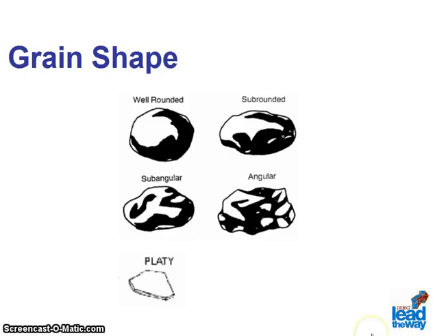When examining samples for grain sizes, the shape of the visible particles can be determined. Sharp edges and flat surfaces indicate an angular shape. Smooth, curved surfaces indicate a rounded shape. Particles may not be completely angular or completely rounded. These particles are called subangular or sub-rounded, depending on which shape predominates. Platy is the name given to these particles which have one dimension relatively small compared to the other two. Clays generally fall into this category.